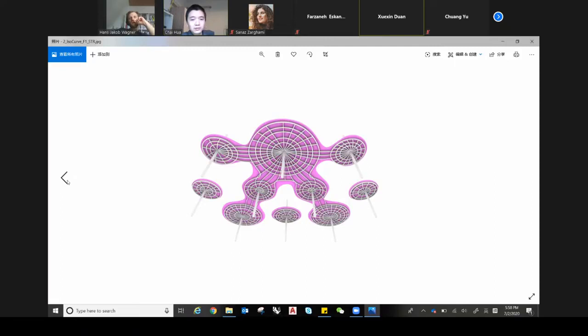If you use the ISO curves to generate beams with the tools we provide, you may get a lot of problems because it's too dense and in some places the segment is too small.